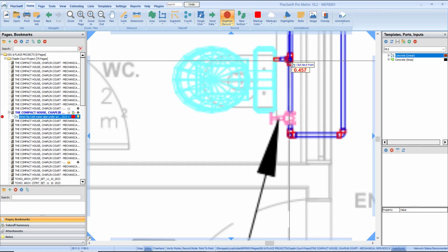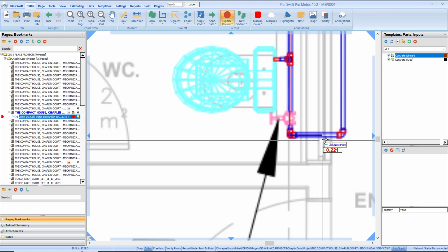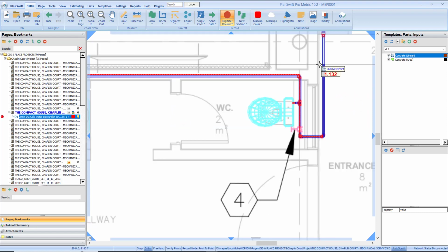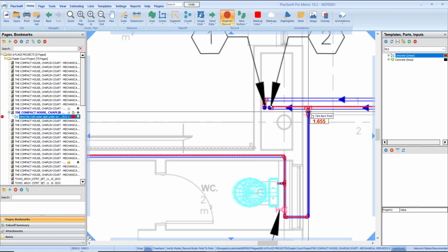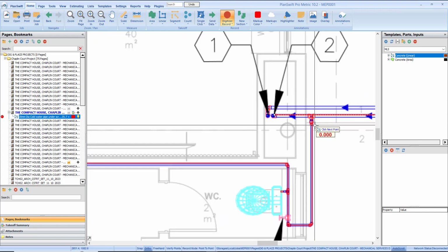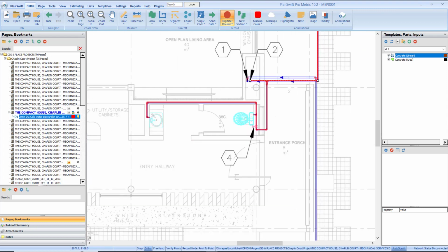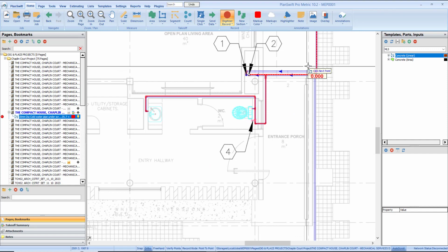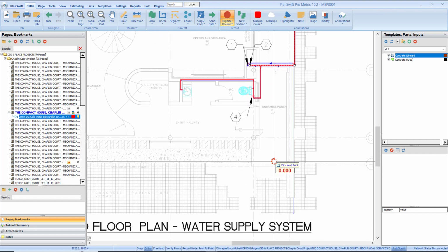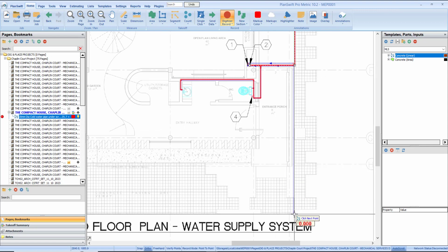Okay, so we have a particular pipe which is supplying this very WC, and from this point to this place there's no height on that, so you might not bother yourself adding any height on this particular place and then to this place. Remember, we're not adding this particular one because this is the one that is supplying our 32 mm riser pipe.